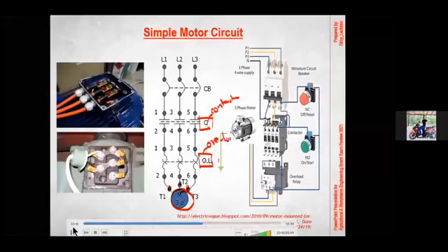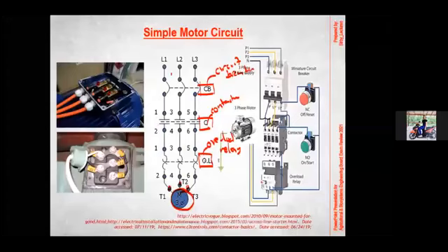Okay, overload relay, and then right here we have the circuit breaker and to the source. Okay, so at that configuration, then there's gonna be a rotation, and let's say we have a clockwise rotation. Now, if you want a reverse direction, then we can just simply interchange this connection. Okay, so instead of having straight, then we'll just have to interchange these connections, and we can get a reverse direction.